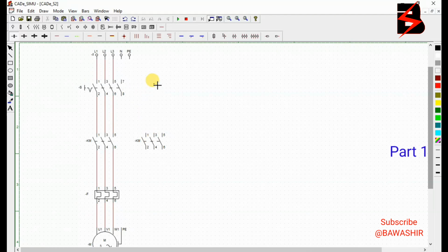So remember I said earlier that we interchange any two phases. So I'm going to take from down the breaker. Remember always to take from down the breaker because it has to control everything here. We are going to get phase 1. It's going to remain consistent. Are you seeing?